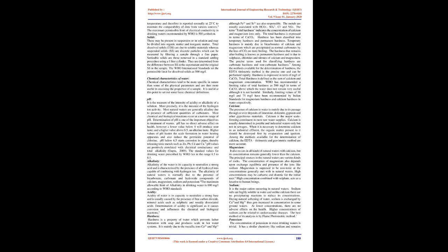pH has no direct adverse effect on health, however a value below 4 will produce a sour taste, and a value above 8.5, an alkaline taste. Higher values of pH hasten the scale formation in water heating apparatus and also reduce the germicidal potential of chlorine.